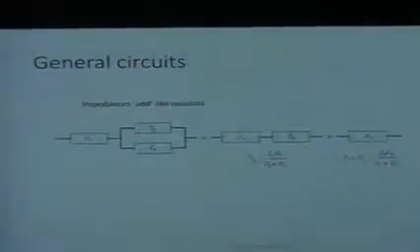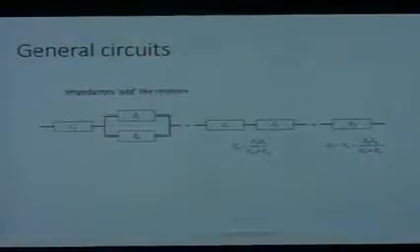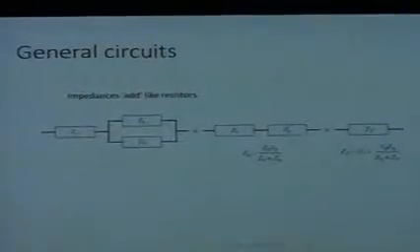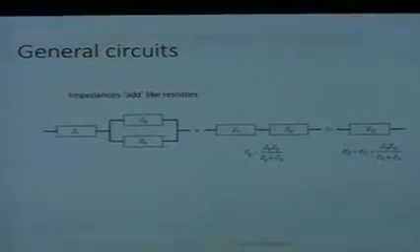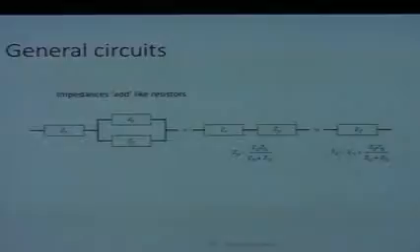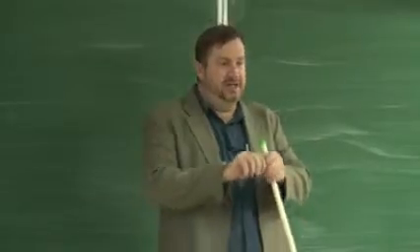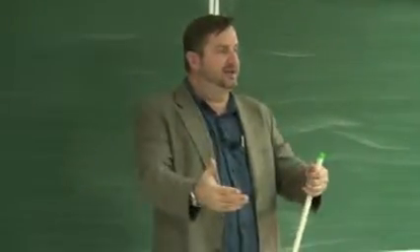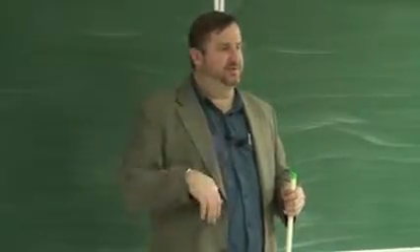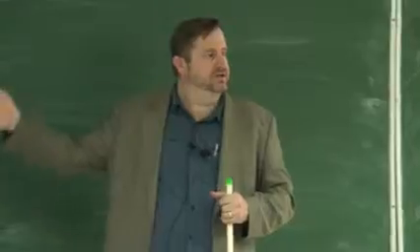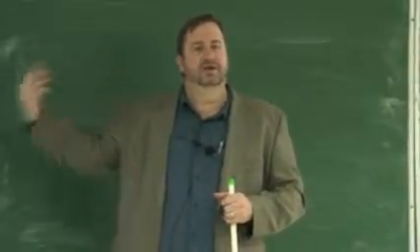So generally speaking, we can add these impedances like we add resistors. That doesn't mean they always just add together. What I mean is, if they are in series with each other, then you add them like series resistors. If they are in parallel with each other, you add them as if they were parallel resistors. Okay? So that makes it a little bit easier, because you probably know that if I have two capacitors in series, then they add like resistors in parallel, and vice versa. So by casting everything into the impedance framework, we're adding impedances the way that we add resistors, which is more familiar to most people, certainly to mechanical engineers like me.